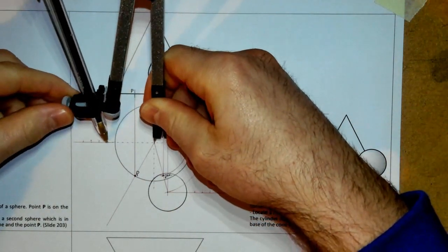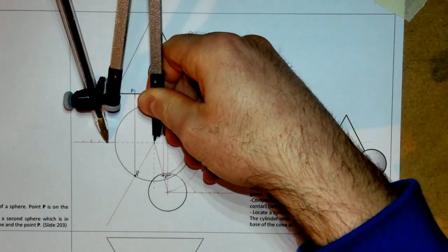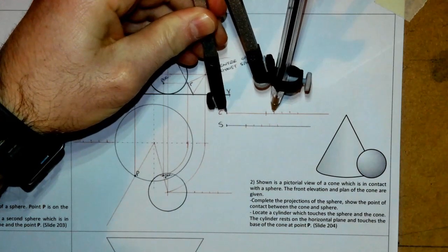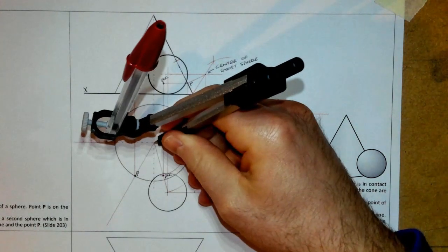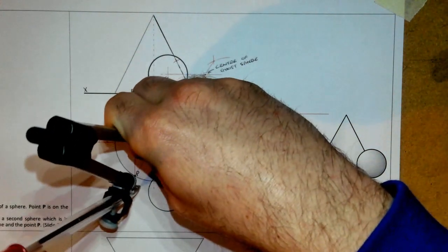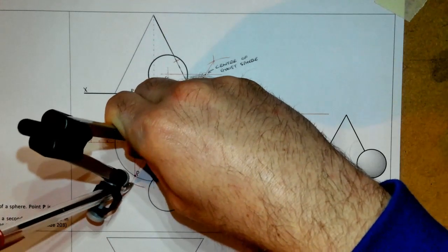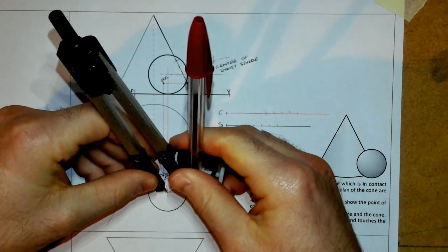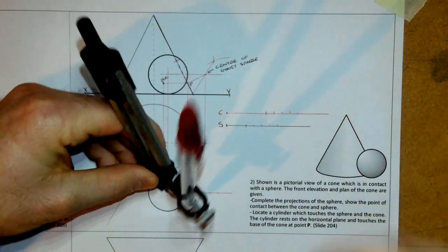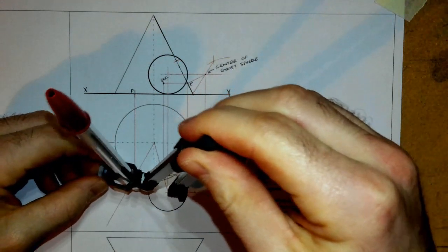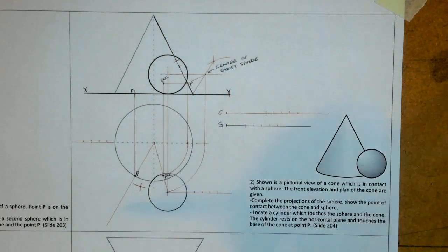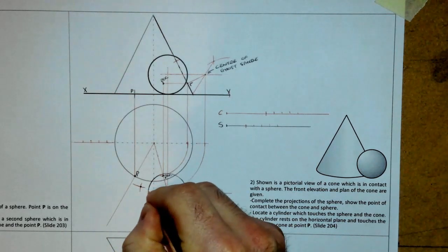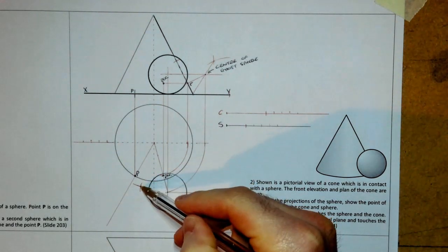So if I was to mark that distance there, which is the first 5 millimeters out, it should be the same as this over here. And it is, okay? So mark that 5 millimeters out, and I assume it's going to be somewhere inside in here. And then I do the exact same with this guy here. Go to the first 5, and it's going to be back in here. Okay, and what we've actually found there is the locus of a point that is 5 millimeters away from our sphere and 5 millimeters away from our cone.